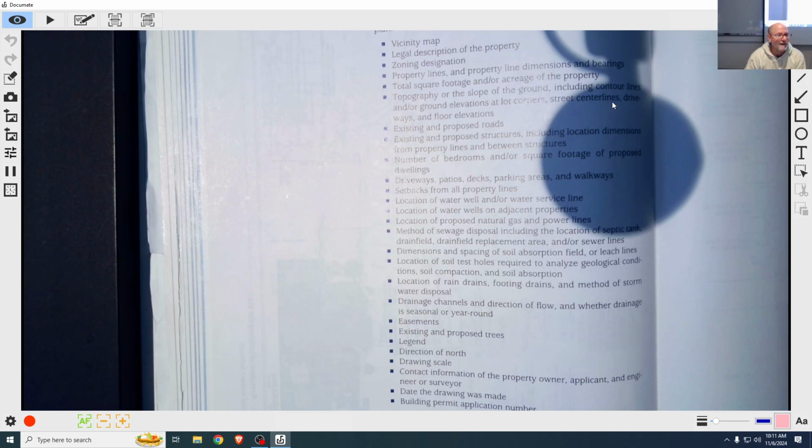It's mostly inside your boundary. So if your property exists and you want to add on to the house, I think the rule around here is 5 feet. You can't breach that 5 foot setback from the property line.